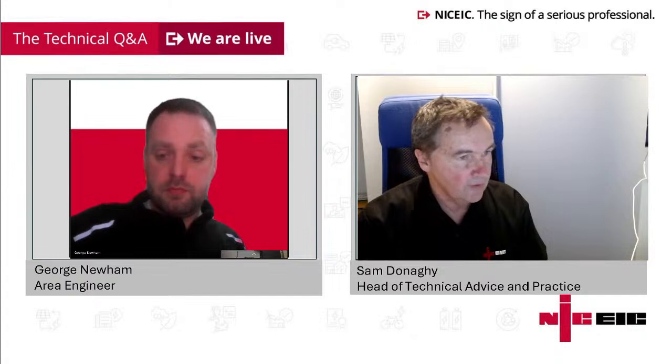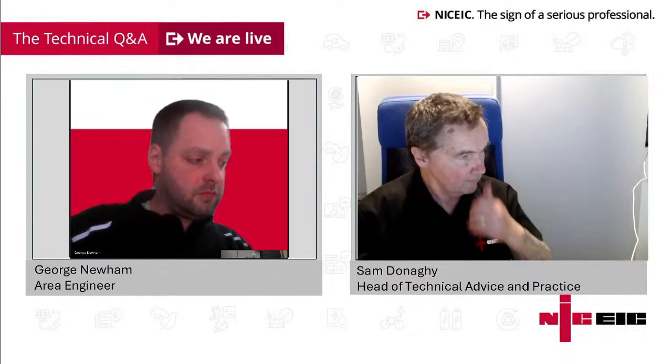Okay, just looking down through. So the engineer has said that no harm whatsoever, might be over the top, but the best way is 5-core armoured, so that you've got an integral CPC. Okay, while we're waiting for some others, let's have a look at